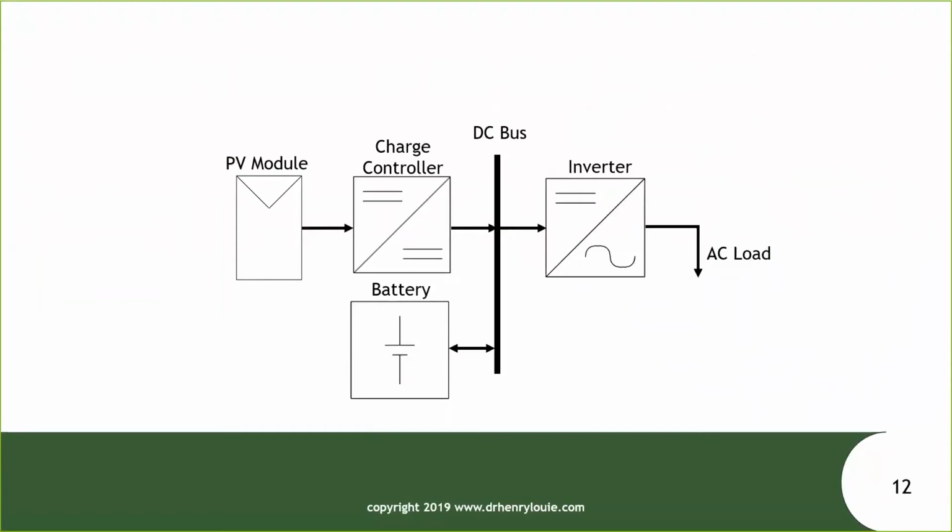Now, depending on your load, you may or may not need an inverter. If your system is primarily designed just for lighting, LED lighting, it's possible to serve that directly from the DC bus. But in most systems, and certainly the systems that I work with, the load is going to be AC. And so you need an inverter. What the inverter does is convert DC to AC, and it's a power electronics device.